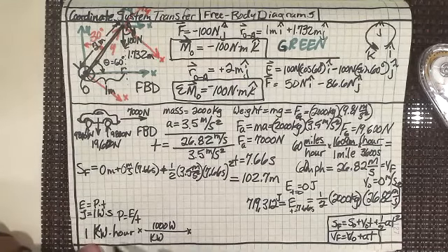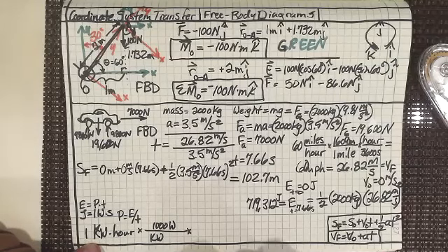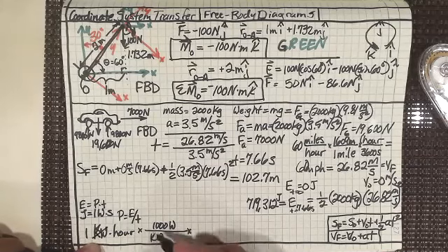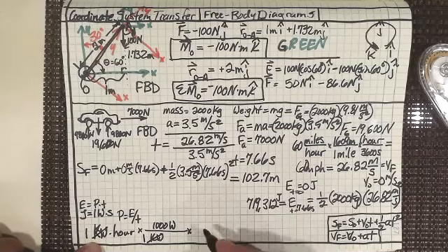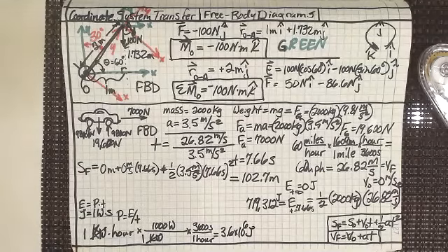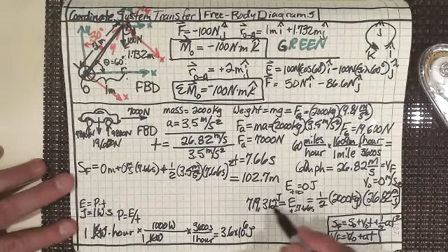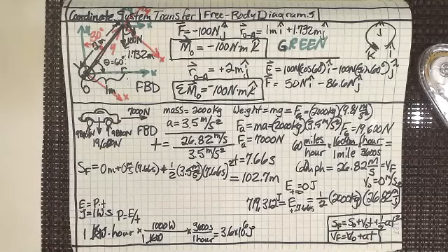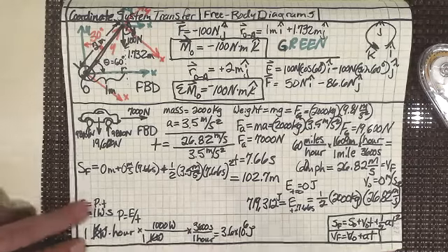Does everybody remember that? So 1 kilowatt hour is actually a unit of energy. Times 1,000 watts divided by a kilowatt. So let's get rid of the kilowatts there. And then let's get rid of the hours and turn them into seconds. So it's in the numerator, so we have to get 1 hour in the denominator, and then 3,600 seconds. And so it's 3.6 times 10 to the 6 joules equals 1 kilowatt hour. So you can see that really here, 719, that's only about 1/4, maybe I should say 1/5 of a kilowatt hour. And that's our unit of electrical energy that you pay for.